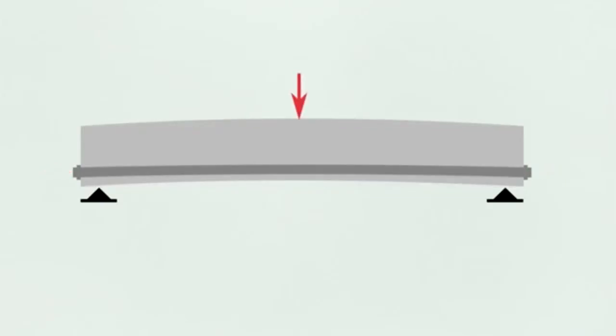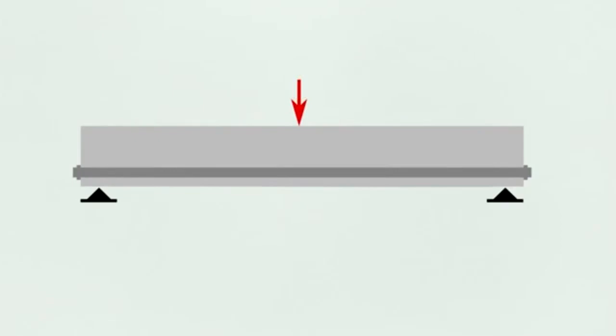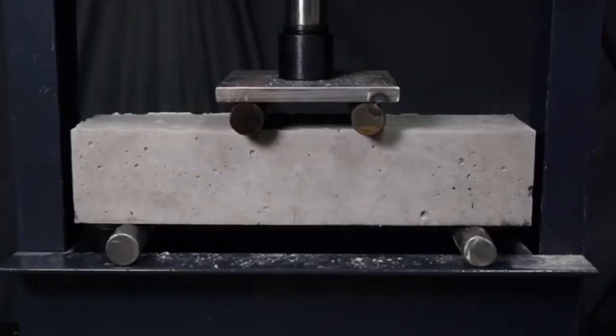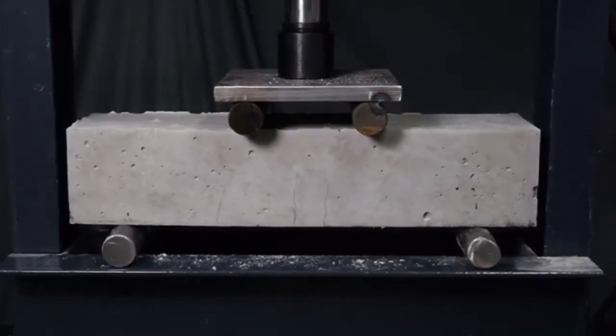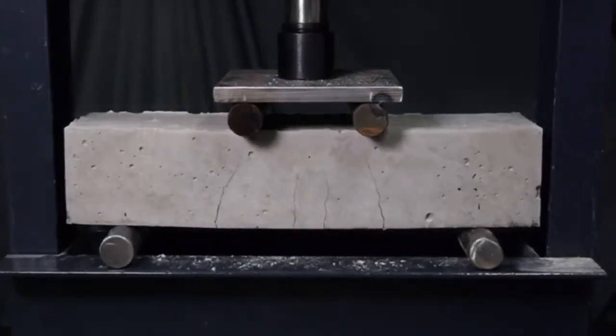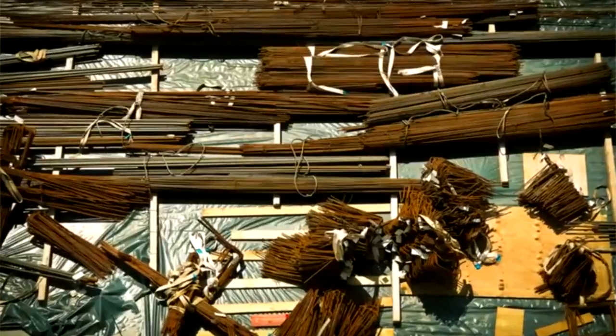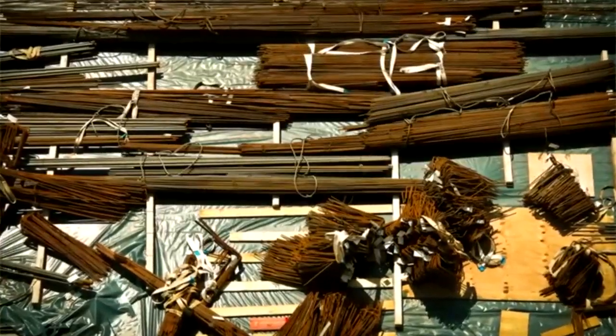One solution to this problem of deflection in concrete members is pre-stressing, or putting compressive stress into the structural member before it gets put into service. This is normally accomplished by tensioning the reinforcement within the concrete. This gives a member a compressive stress that will balance the tensile stress imposed in the member once it's put into service. A conventionally reinforced concrete member doesn't have any compression to start with, so it will deflect too much well before it's in any danger of not being strong enough to hold the load. So with conventional reinforcement, you don't even get to take full advantage of the structural strength of the member.